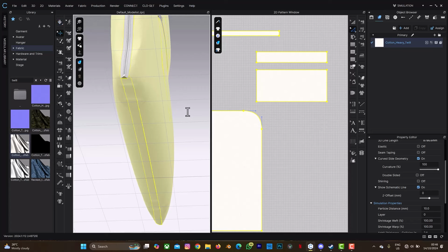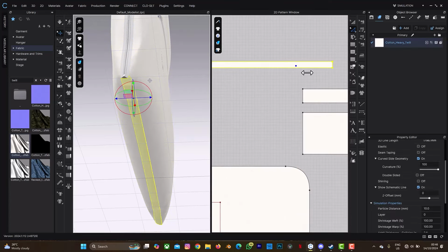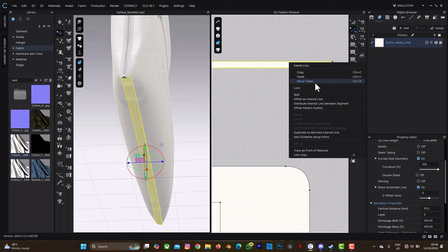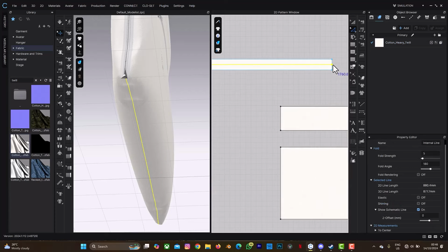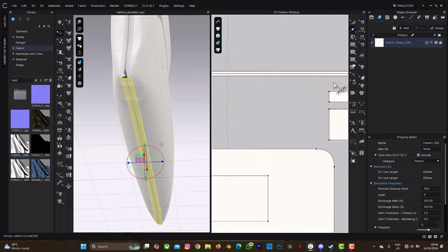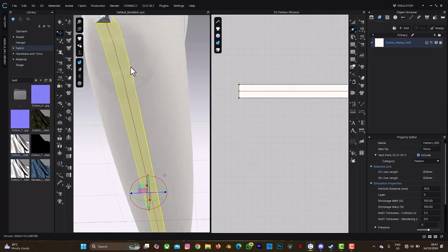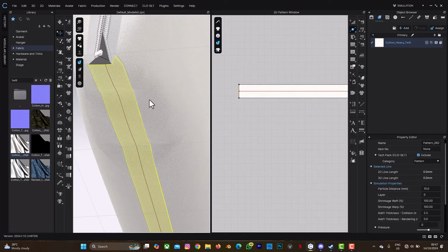So I'm going to stop my simulation. Okay, this is this stuff below. Select it. Okay, let's select Z on our keyboard. Select this line, right click, then select distribute between line. Yeah, select OK. And we select X on our keyboard, create a point here. Select this side again, just the center line, create a point there. So I want to close this spacing here. So we've done that. This thing can only be done in the 3D view. Let me simulate it again because that's scattered.